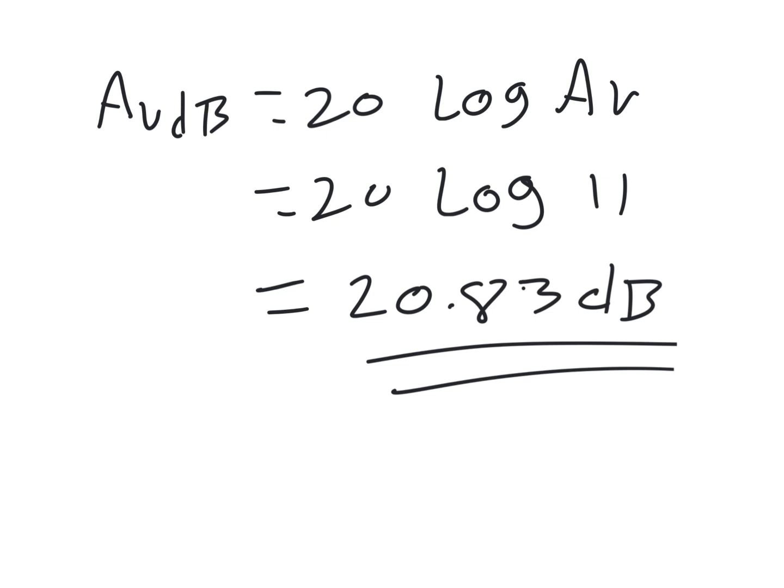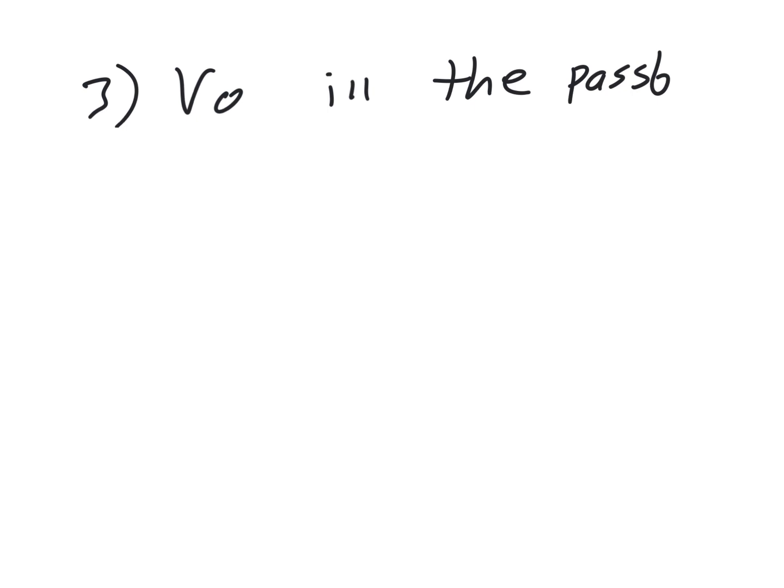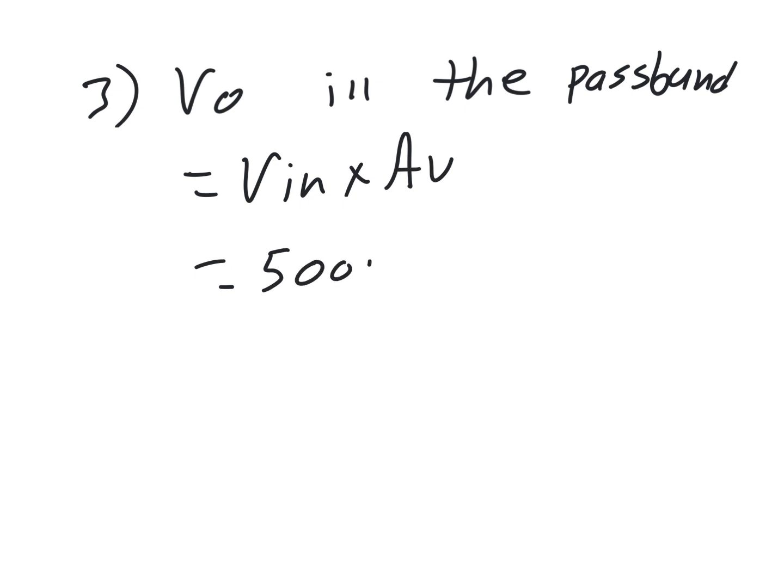All right. And the output voltage in the pass band equals Vin times AV: 500 millivolts times 11.